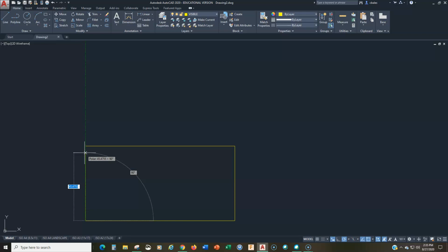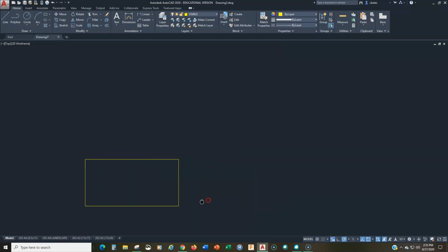The other way to do this, as I'll show you in the next little square that we're drawing, is to use Ortho, which is also good. So I'll show you how you do that. All right, so that would be the space where the front view is going to be occupied. And just to get things going in here, I'm going to switch to Ortho. So this is the Ortho toggle on the status bar. So I click on that, turn Ortho on, and then I'm going to go up to line. And what I'm going to do is track from this point.